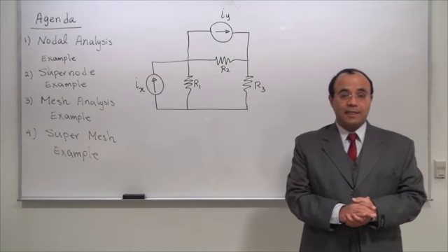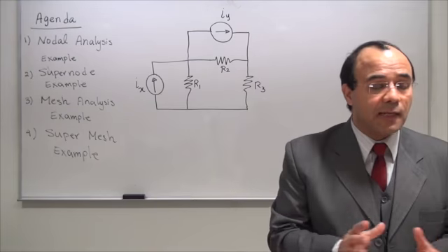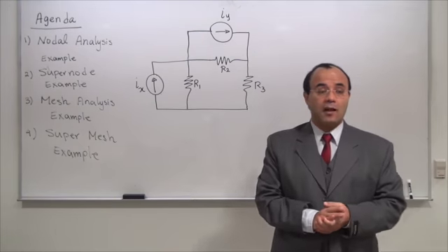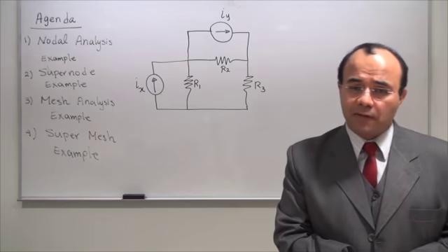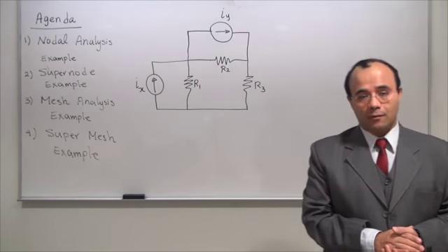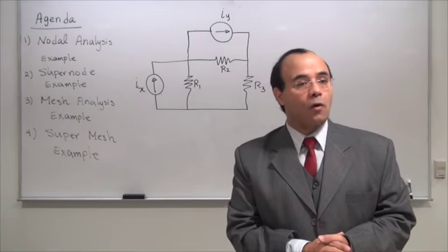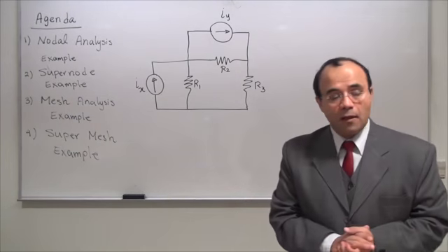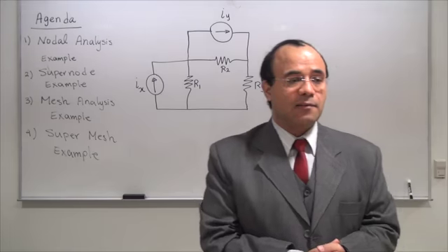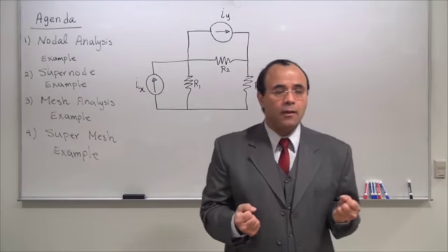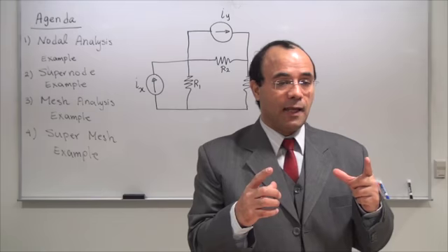At the same time, we said that if they are in parallel, and you can verify that nothing else is going to come in between, you can actually identify the currents according to the G rule. The G rule means that the current of a specific component is going to be proportional to the inverse of the resistance. It's 1/R, and that's why we call it the G rule. When we have two components in parallel, the textbook and everybody else says that you can actually simplify the G rule. Two components in parallel can be replaced by one component in the following fashion.